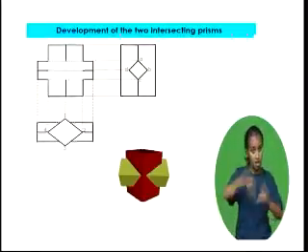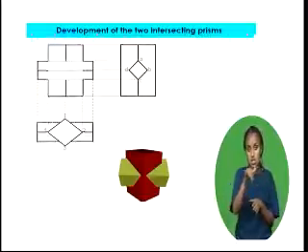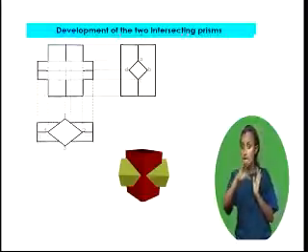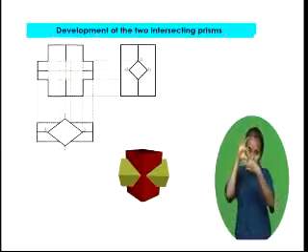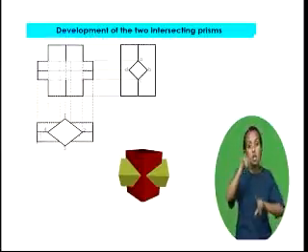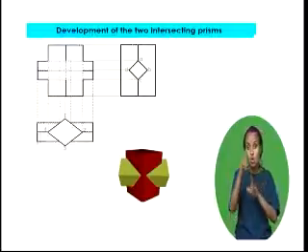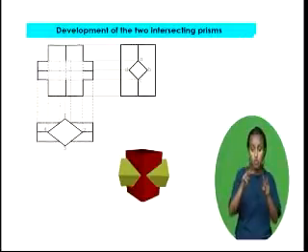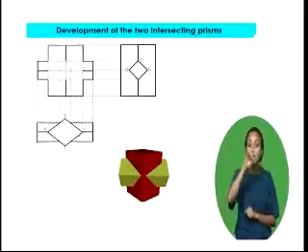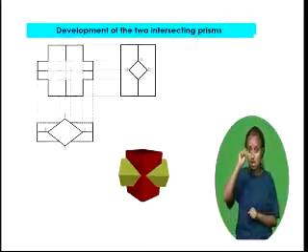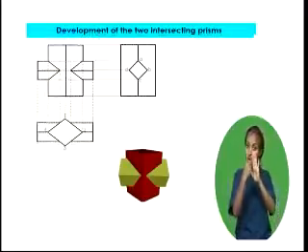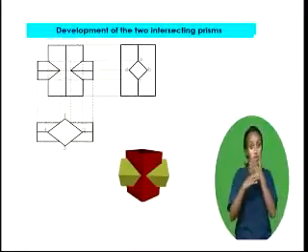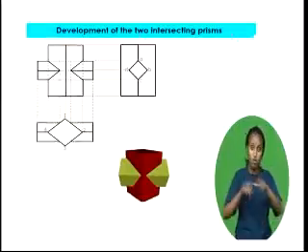Project the same points A, B, C, and D from top view down to front view to intersect the projection lines of corresponding points from end view and establish the required piercing points that lie on the line of intersection. Connect the piercing points obtained at step 4 to complete the line of intersection of the two intersecting prisms.